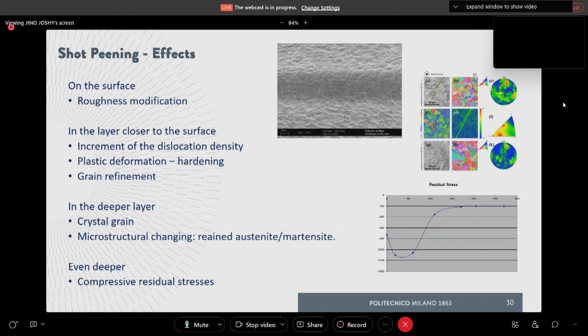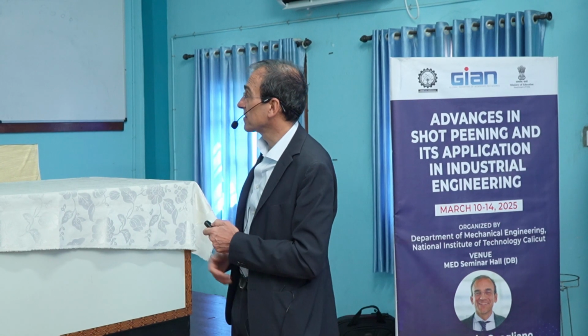If we shot peen a crankshaft or a shaft or gears, we start from very fine surfaces because this is what we want for the service condition. But it's curious that if we start from additive manufacturing, this is not true anymore because the surface roughness of the as-built laser powder bed fusion part is poor. So the treatment must be completely retuned.